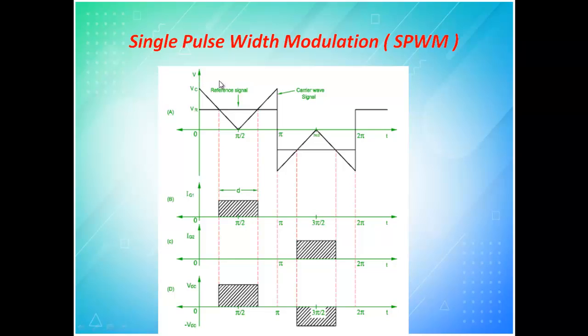So you can see here, if I move this line either below or above, if this VR reference signal is brought down, the voltage will reduce. If I increase it, the voltage will increase, both in width as well as in height. Now if I move this up, the area of this will increase. When the gate increases, your voltage will also increase.